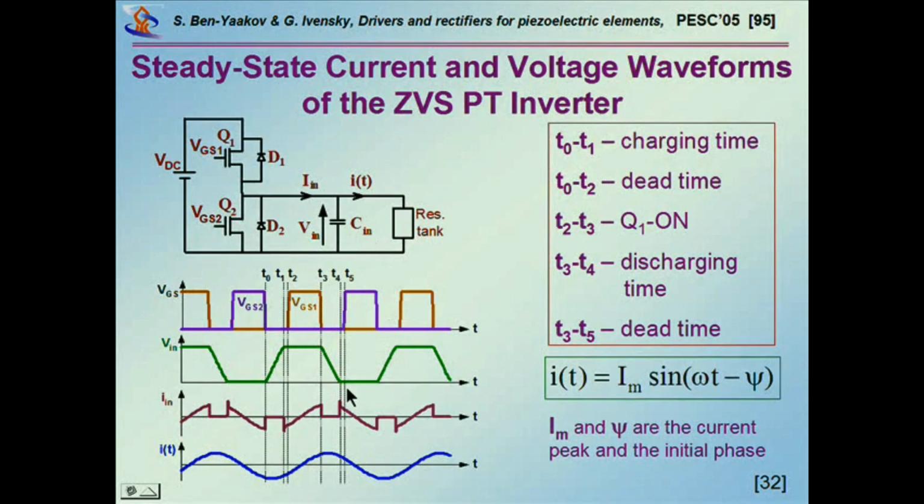Here we see what we'd like to get if indeed we have an inductive behavior, including the input capacitance. That is, the inductive behavior should overcome this input capacitance, and the net result would be an inductor of low enough impedance to carry the current needed for charging and discharging the capacitors.